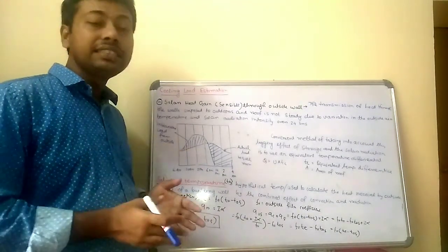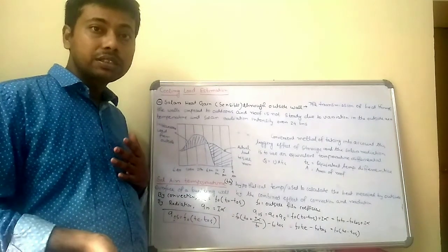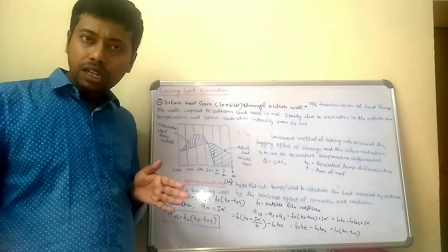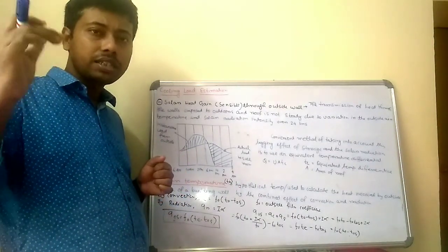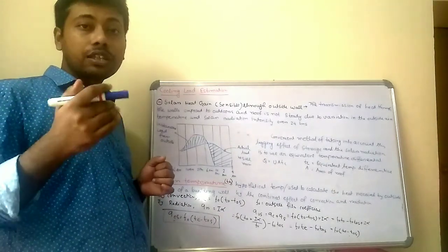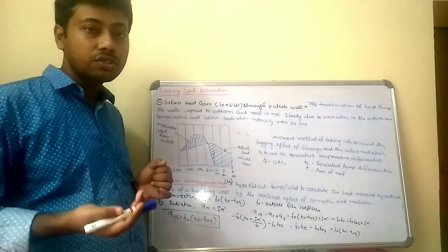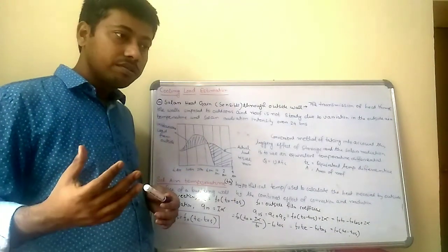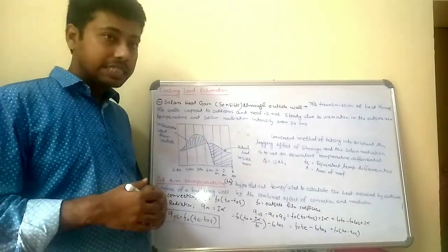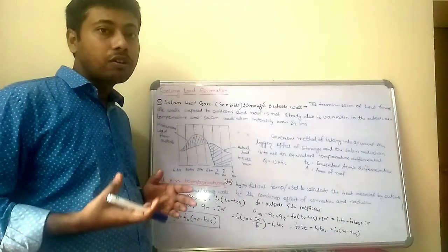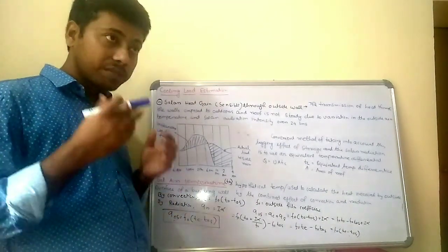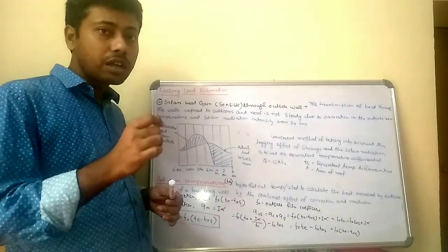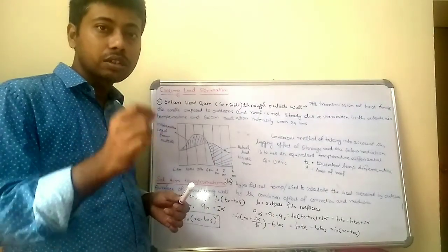That Tc depends on the thickness of the wall, the direction from which the solar intensity comes, and the material the wall is constructed from. So Tc depends on those variables. There are some charts you can go through to see which variables the value of Tc depends on and how. From that particular chart, depending on the thickness, the Tc value varies. So you have to consider all those things when you do the cooling load estimation.